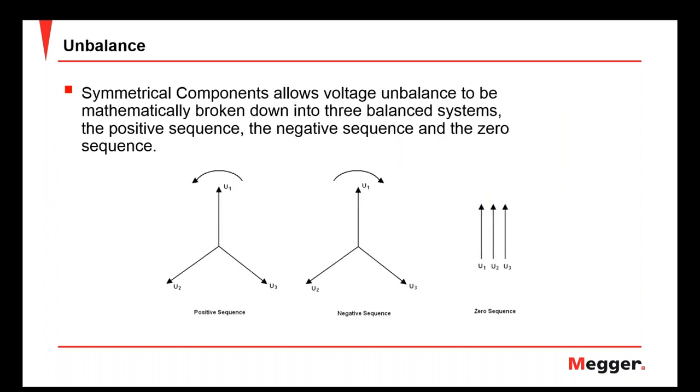So there's another method that's also done, and this is the method that's typically referred to in power quality standards. This is looking at symmetrical components. When we look at symmetrical components, what we're really looking at is what's called the positive sequence, negative sequence, and zero sequence components. This has to do with the magnetic field rotation around the wire. Basically, positive sequences rotate in the same direction as the fundamental, negative in the opposite direction of the fundamental. Zero sequence have no rotation. I'm going to explain this a little later in the presentation.